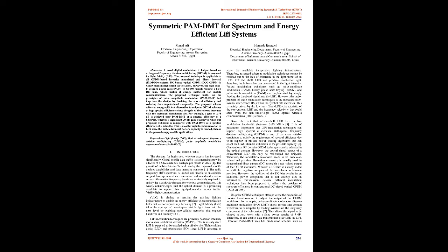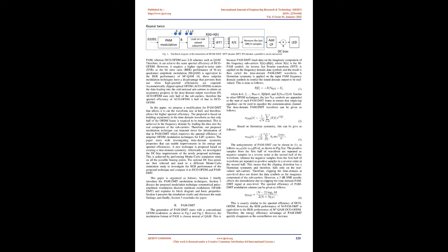Pulsed modulation techniques such as pulse amplitude modulation, PAM, binary phase shift keying, BPSK, and pulse width modulation, PWM, can be implemented by simply feeding the baseband signal into the LED. However, the major problem of these modulation techniques is the increased intersymbol interference, ISI, when the symbol rate increases. This is mainly driven by the low-pass filter, LPF, characteristic of the conventional LED and the frequency selectivity that could arise from the non-line-of-sight, NLOS, optical wireless communication, OWC, channels.